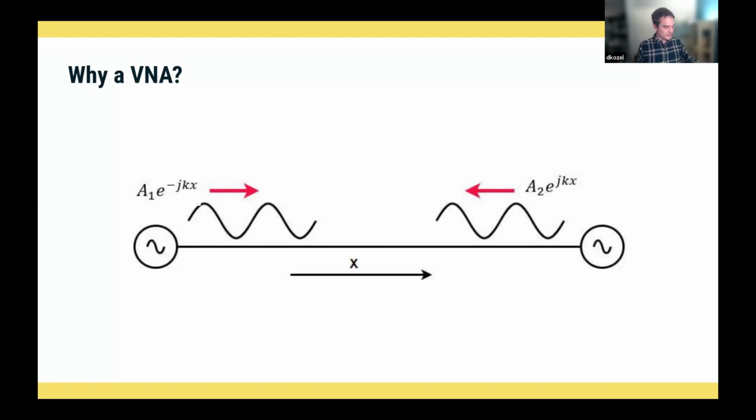We all know, well, hopefully folks are familiar with the concept that if you don't connect your antenna to your radio, it's going to blow up, or you might cause damage to the output. Why does it cause damage? Because all of that signal that you're transmitting out reflects backwards. That's the core idea. We want to be able to measure this ratio.